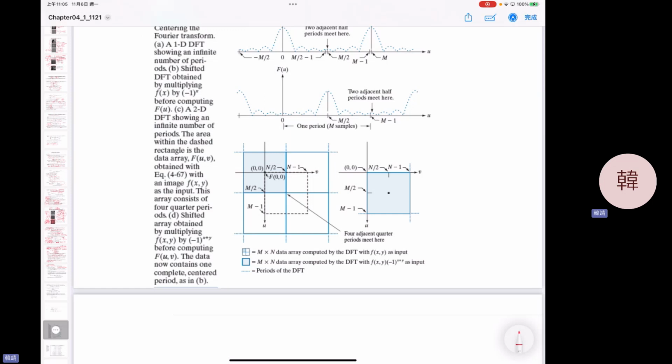So you can expect this image and this image have exactly the same magnitude spectrum. It will not affect the magnitude, only the phase spectrum, which we will see later will be changed. How about this one? This is exactly the same rectangle but located at 45 degrees. So you expect the result will be like this one: the angle changes and the magnitude spectrum is the same.